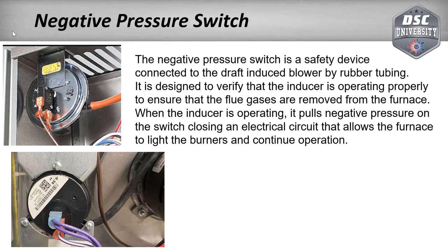Another thing, on some of the older models before 1992 that had pressure switches, guys would sometimes just go in there and take the wires off the pressure switch and jump them out, which would set up a condition where that furnace could potentially just sit there and run forever, regardless of what's going on.